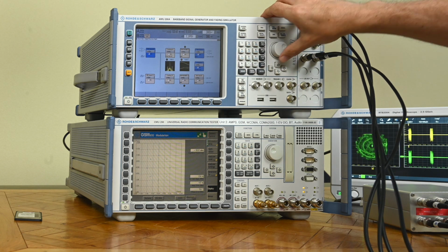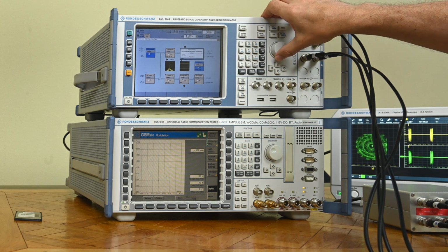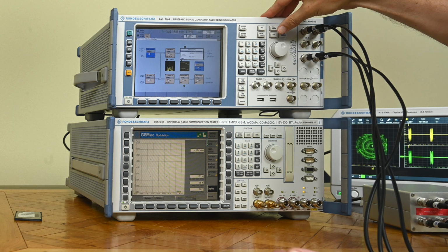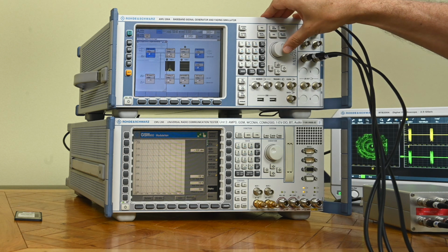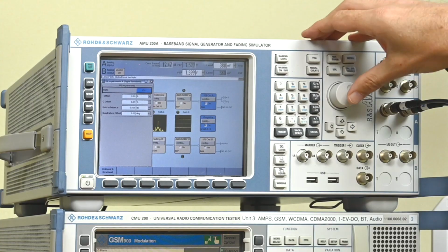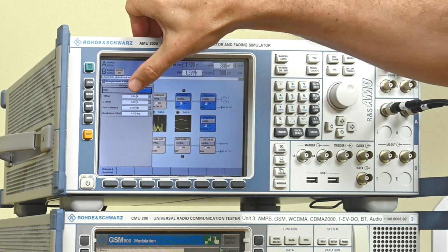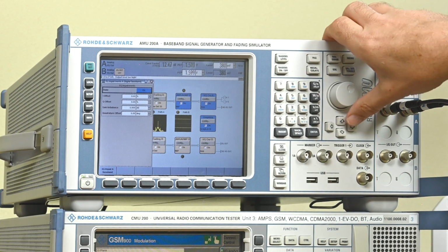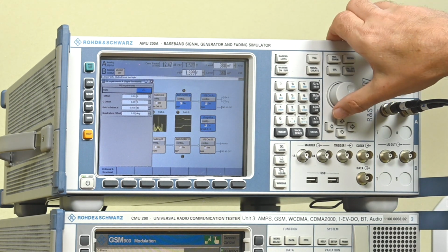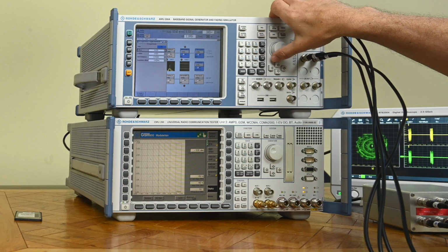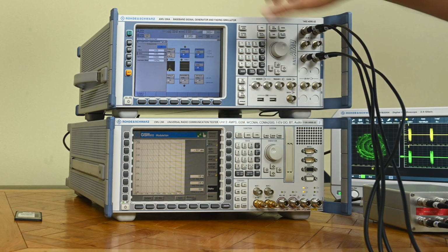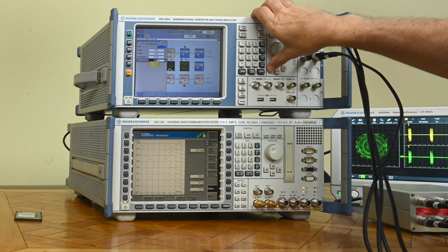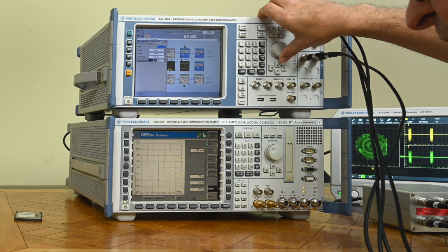And I'll try to demonstrate the same thing when we do IQ impairment. So we're going to deliberately do something wrong with the IQ signal. Let's see what we got here. Let's turn this unit on. So we can have an I offset, a Q offset, a gain imbalance, and a quadrature offset, so the angle under which things are happening. I'm not going to go to the I and the Q offset because we already know we're looking at normalized values. But let's try the quadrature offset. It's in degrees. And I'm going to turn this button now.